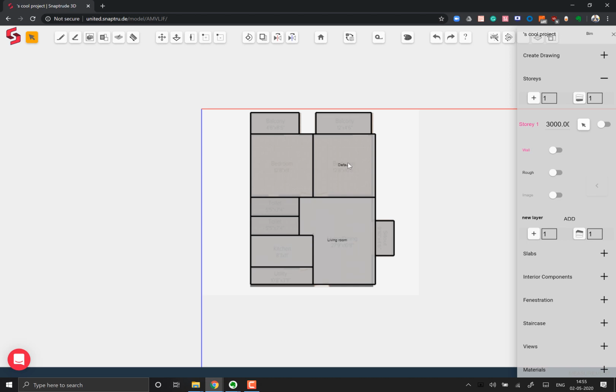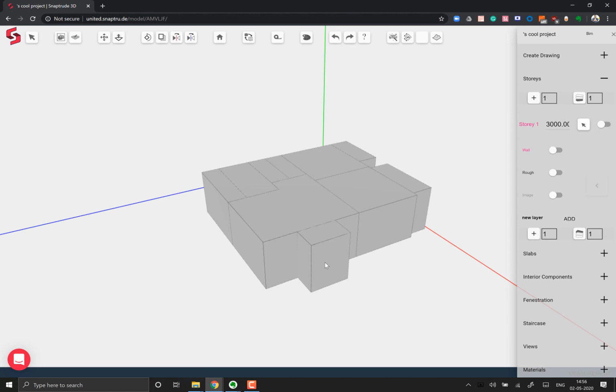Similarly, I'll do it for this bedroom. I'll double click over here and the menu appears. I can start typing bedroom and it'll show me a recommendation while I just press B and E and press enter, it'll become a bedroom. So these labels can not just be added in 2D, they can also be added in 3D. I will go back to the 3D view and try to complete the labels.